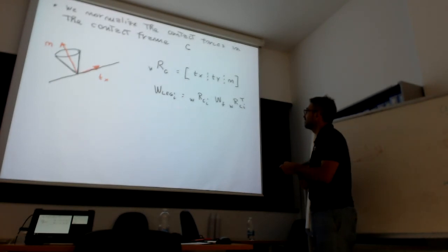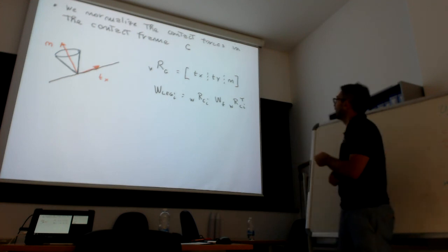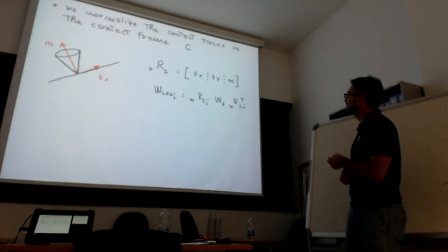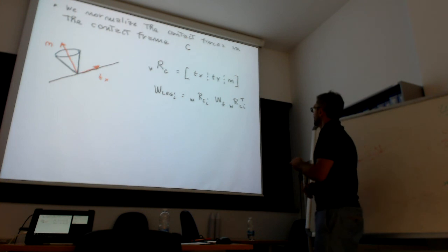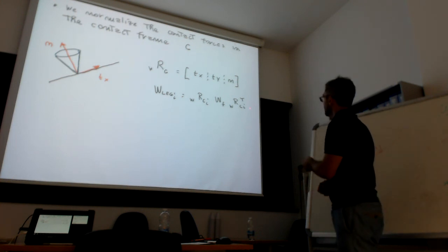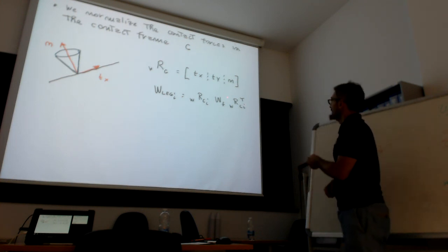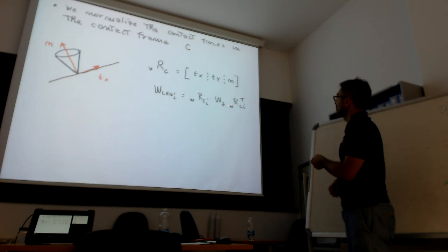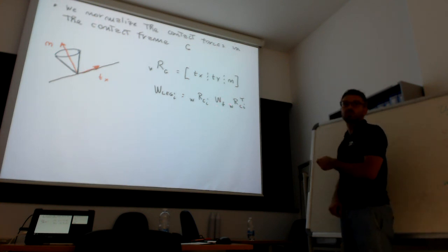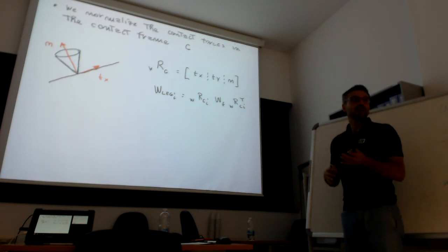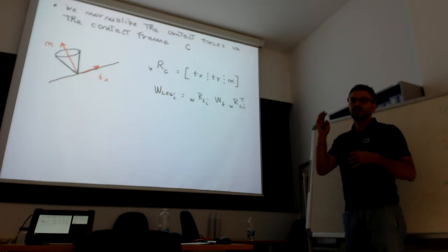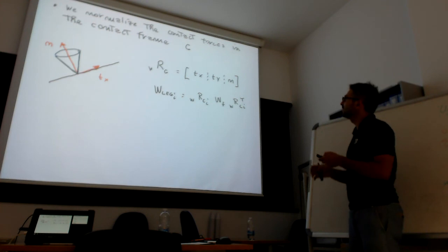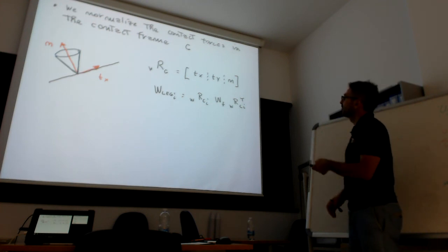This means that we define for each leg this weighting matrix that maps, let's say, forces from the wall frame into the contact frame. Then you have again a weighting matrix to selectively minimize the tangential or the normal forces, and then you map back to the wall frame.